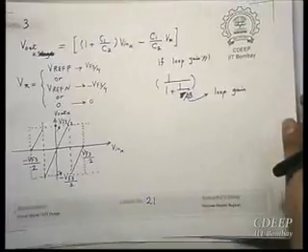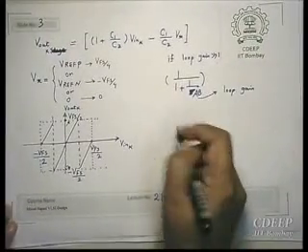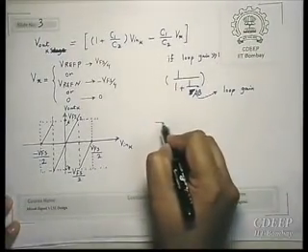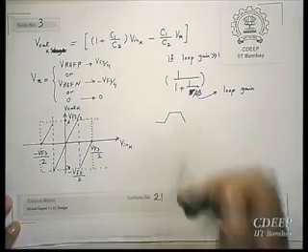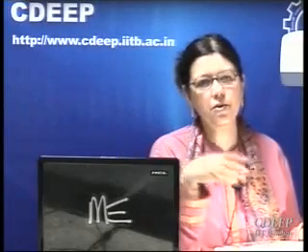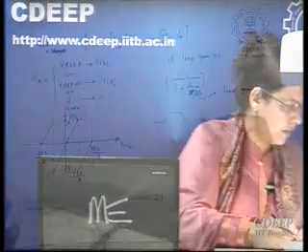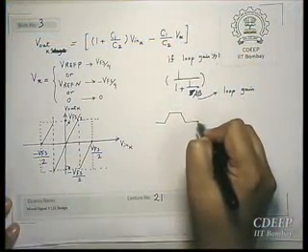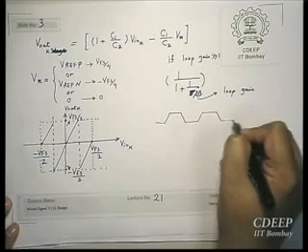Okay. So now again there will be 3 phases of clock. I tried to save the paper, but it is the same as what we had before. Do you remember we had 3 phases? Phi 1, Phi 2, Phi 3. And in fact, one of the phases was just to avoid input dependent charge injection. So here also it is the same thing. They actually have 3 phases, but mainly 2 phases.